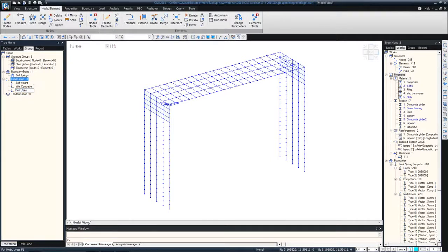So sometimes what we do is, instead of modeling the boundaries for the abutment, we don't go into the abutment soil structure interaction. Rather, we apply the pressure on both the abutments and ignore the boundaries. So that is also another way of applying earth pressure and say surfacing.